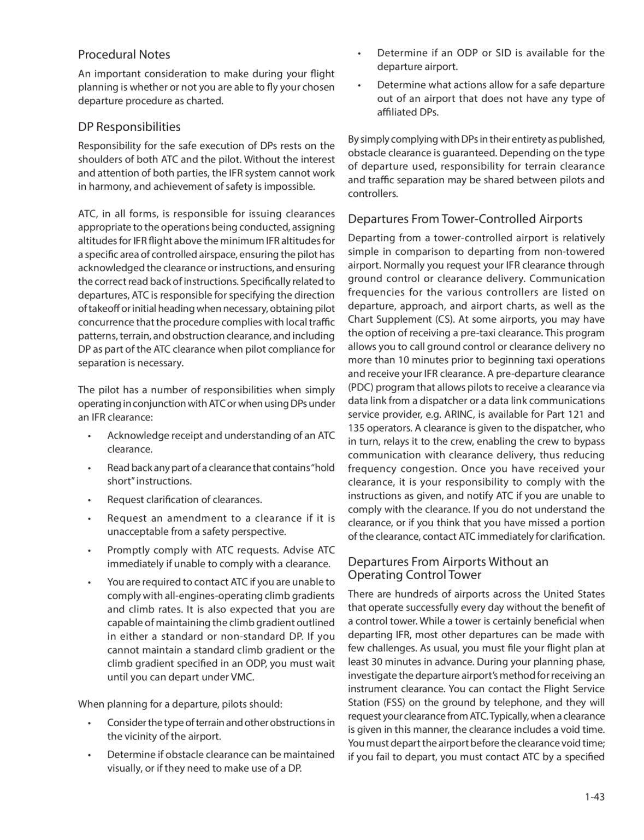Departures from airports without an operating control tower. There are hundreds of airports across the United States that operate successfully every day without the benefit of a control tower. While a tower is certainly beneficial when departing IFR, most other departures can be made without challenges. As usual, you must file your flight plan at least 30 minutes in advance. During your planning phase, investigate the departure airport's method for receiving an instrument clearance.